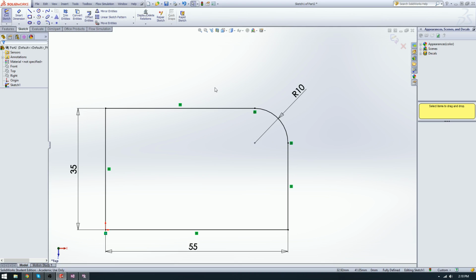It's nice, it's a good feature. Sometimes though, you really want to look into it yourself, because SolidWorks may know how to fix whatever problems you have, but it doesn't know what you're trying to do. It doesn't know your design intent. So it's always good to look in and make sure that a solution is going to work for your overall sketch, and it's not going to break something later on down the line.